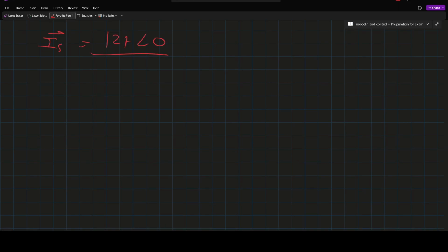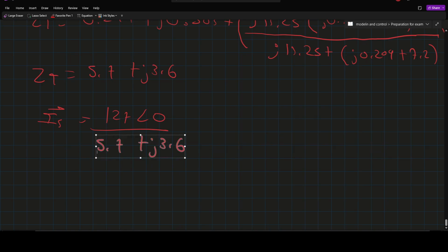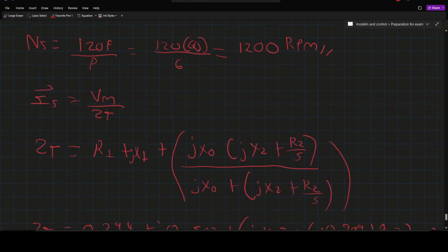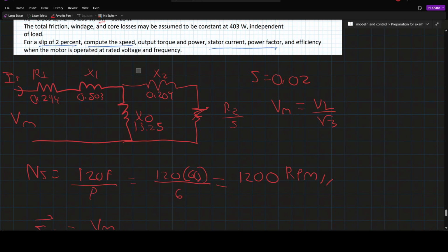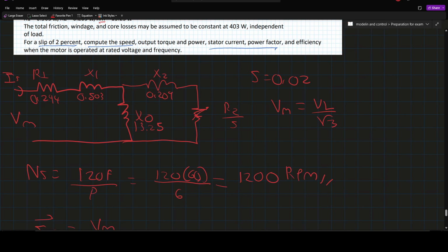Okay, now down here we have our equivalent impedance, and this gives us 18.83 at an angle of minus 32.3 degrees. Okay, and now for IR, we know that we have here a current divider, and we're interested in the current going through this side.